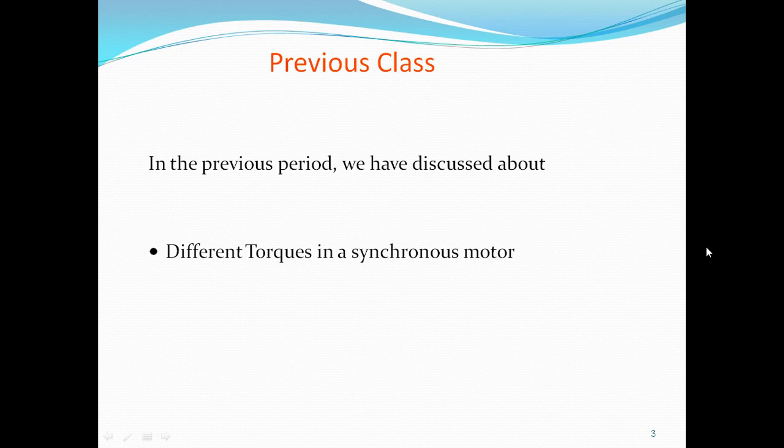At a particular instant, when you apply the load, alpha increases, back EMF EB increases, then armature current increases, then torque increases. So the process will continue until it bears the load. So alpha also increases. At one particular point, the motor is not able to bear any load. At that time, the motor comes out of synchronism and the motor stops.